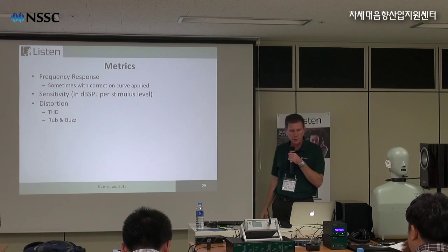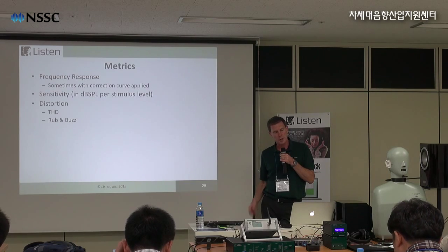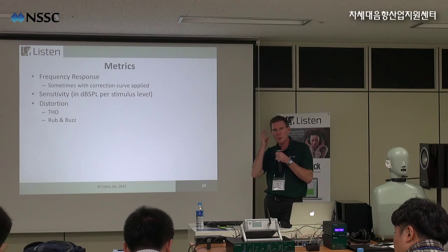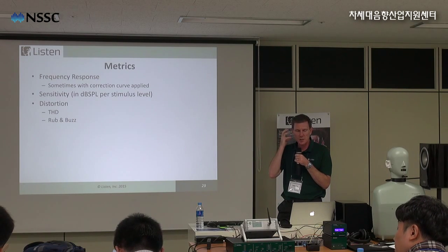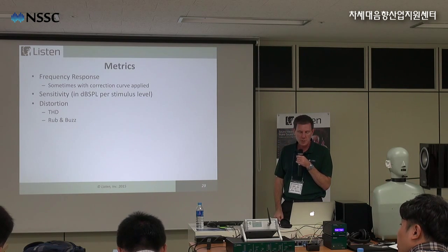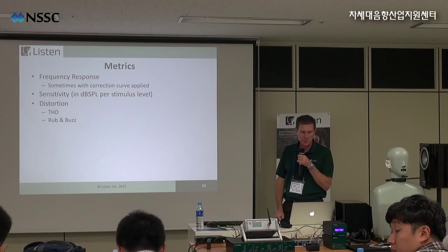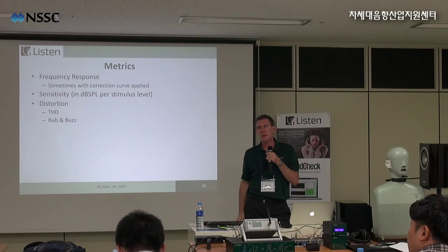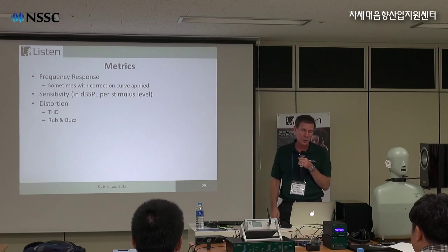Distortion. Now, if it's R&D, typically total harmonic distortion, but if it's production, we want to know if there's any buzzing in there, if something's not right, a part's loose. So we'll talk about rub and buzz, but that's typically a manufacturing problem, not a design problem.